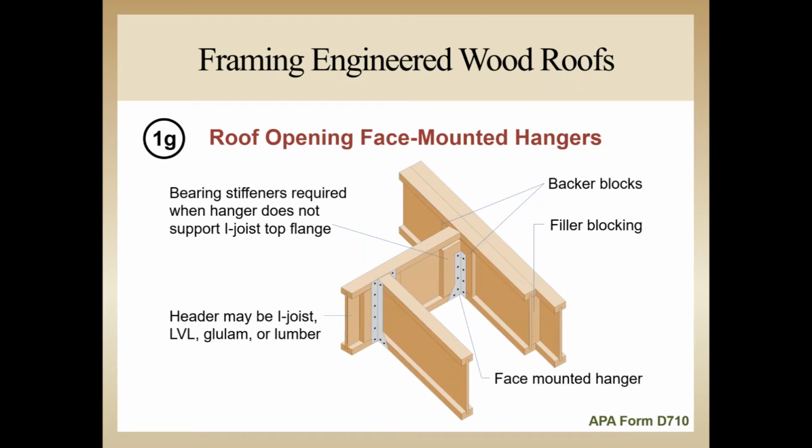Obviously, with any of these assemblies, loads must be calculated to make sure that the header beams are sized correctly. We may find ourselves using LVL, glulam, or another type of compatible depth engineered wood beam material. Otherwise, everything else is the same as in detail 1F.